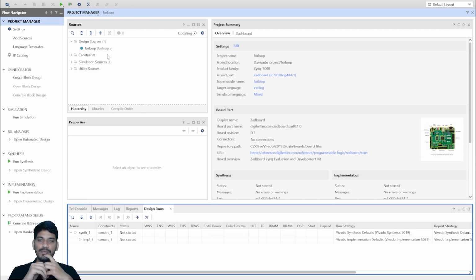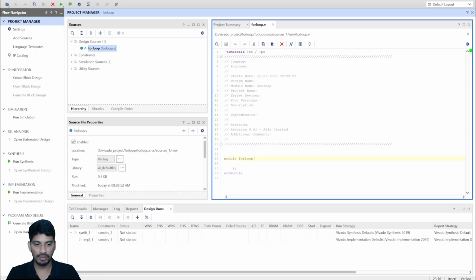We'll use the same example that we discussed in the theory: I have a state bus, and in that state bus I want to assign alternating zeros and ones, right? So my output is, see, I'm both declaring the port as well as declaring the variable of the port. Output is a register called state, which is a 32-bit register, so 31 down to 0.